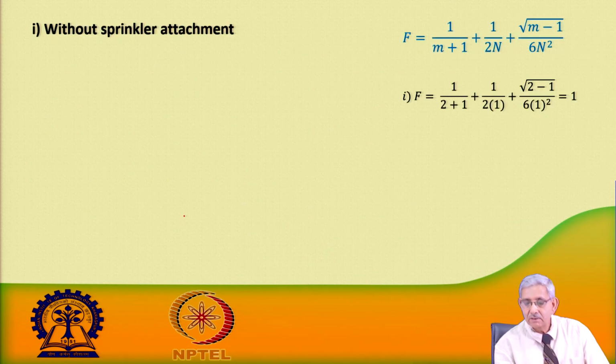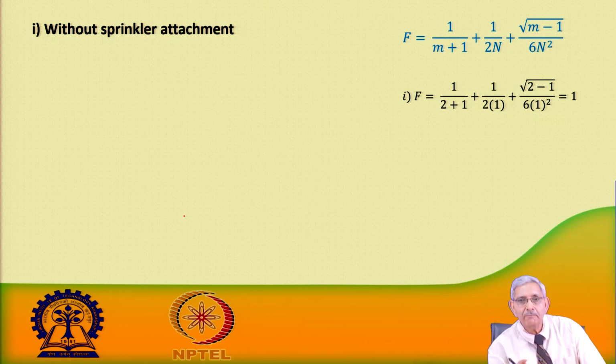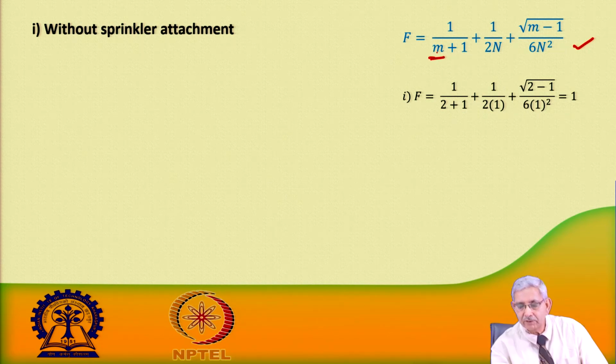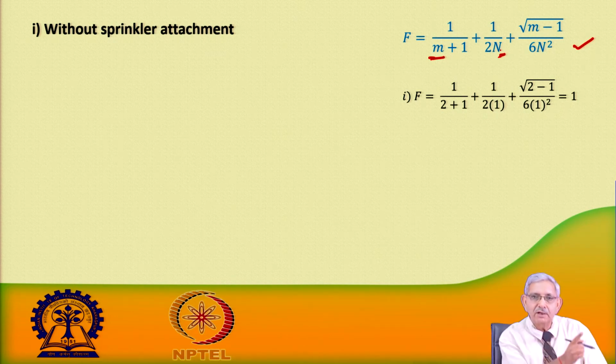We are particularly considering when the spacing between the sprinklers is the same. So, this reduction factor formula is applicable, and the value of m is known to us for the Darcy-Weisbach equation. m is 2, and then number of outlets, it is a simple one, means there is one water entering from the inlet and going out.